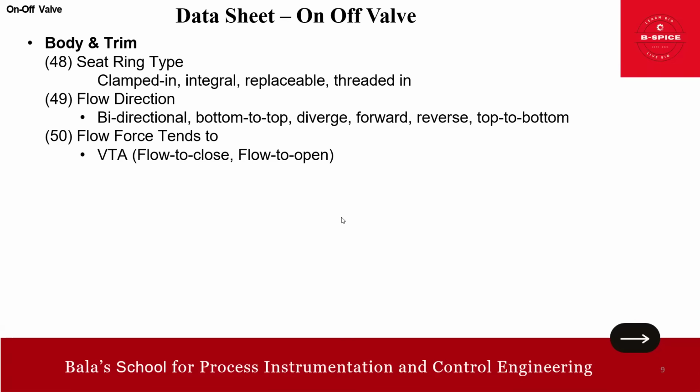Then one more point here, friends. Flow force tends to. Of course we can get it from the vendor, but we also need to know this. So flow to close, flow to open. What is this flow to close and flow to open? Flow to close is also known as reverse flow, or in a globe valve, flow over the seat. In a globe valve, we call it flow over the seat.